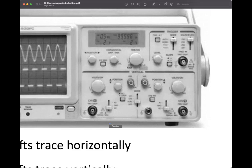So how do you actually play with this? From here, can you see? This is your positioning when you move the signal up and down. And this is your gain, your Y gain, where you change your magnitude to become greater or lesser.